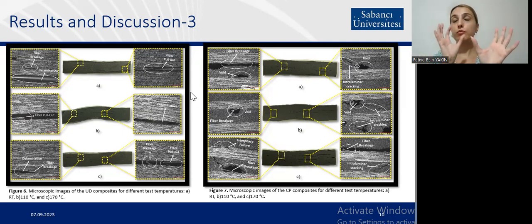The fiber phase carries the load, and the matrix phase dissipates the load. Because of the cross-ply nature, the 90 degree lamination cannot carry the load very well. Therefore, the optical microscope is the proof of why our ILSS results came out like that.